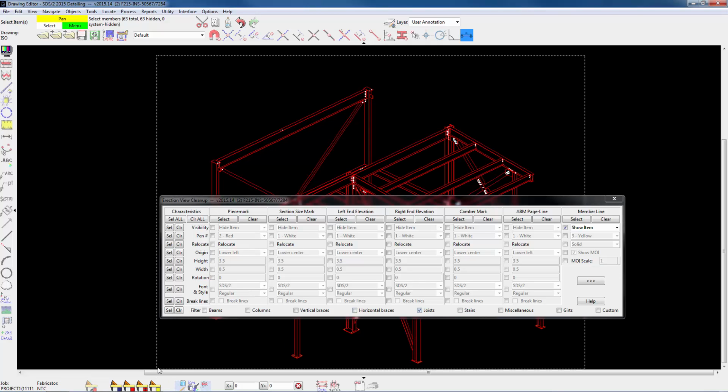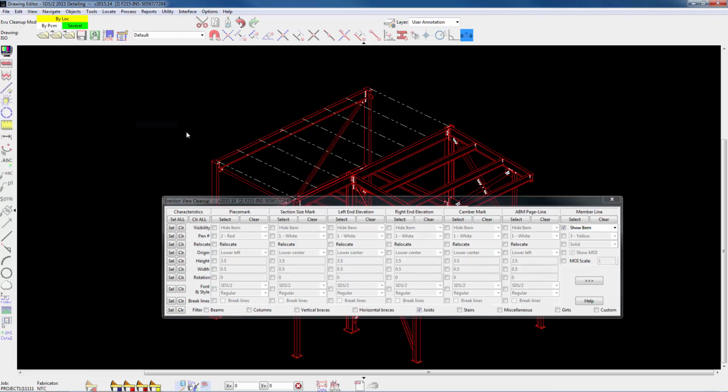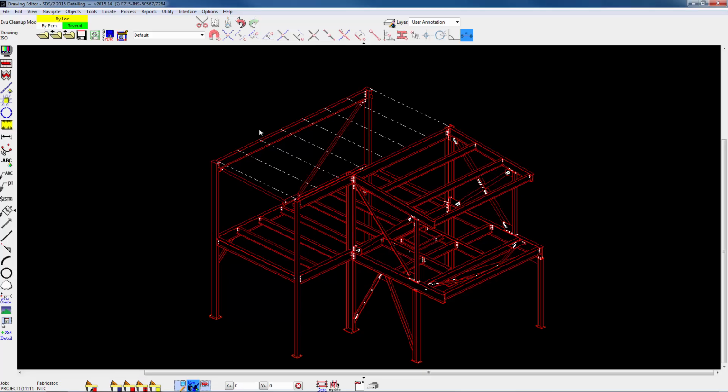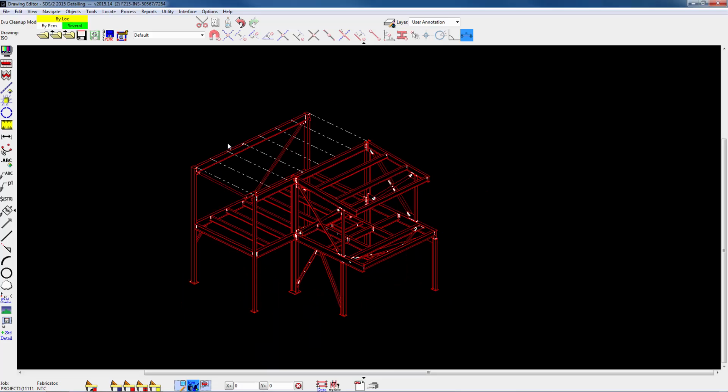Then I'm going to put a box around the building again, menu button, left click for menu, hit OK, and cancel out of that command, and now my bar joists show up. So now I'm going to hit escape here to get out of this command since there's no return button. Now I'm back to my select items mode.